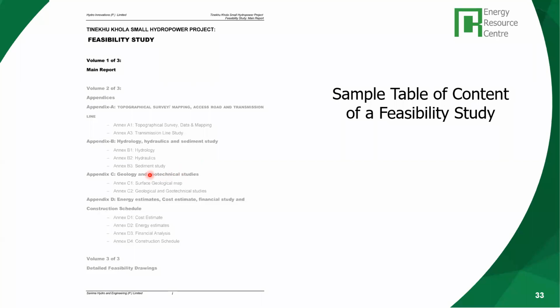Then also, depending on the site condition, a sediment study, because sediment can have a very negative impact on the turbines. It would damage the turbines. So you need a sediment study, so that your sediment handling, your sediment settling basin, is designed properly.